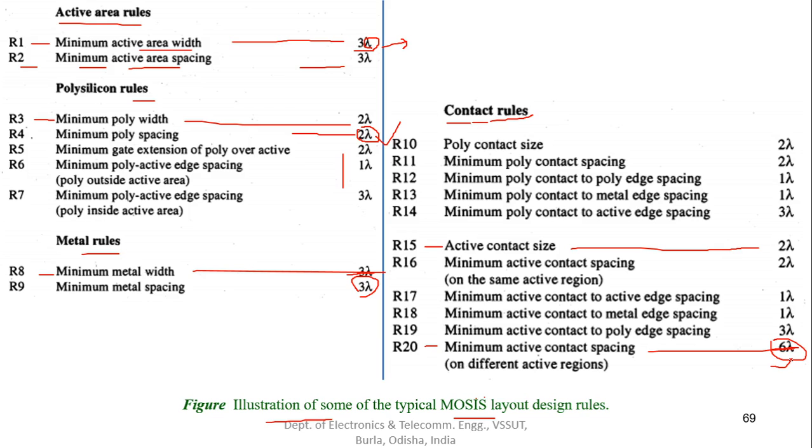So if such a circuit is designed which does not follow the layout design rules, then there are pretty high chances of the chip malfunctioning after fabrication. There will be no guarantee given by the fabricators that if they fabricate it, that chip will work or not. So this is the minimum thing. These dimensions should be followed. Why should they be followed?